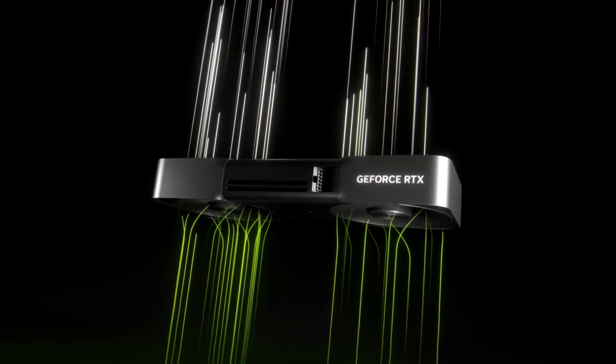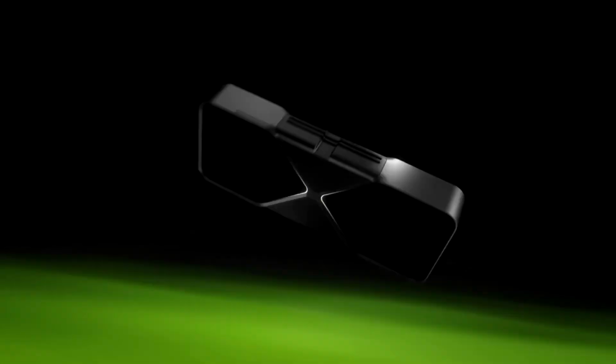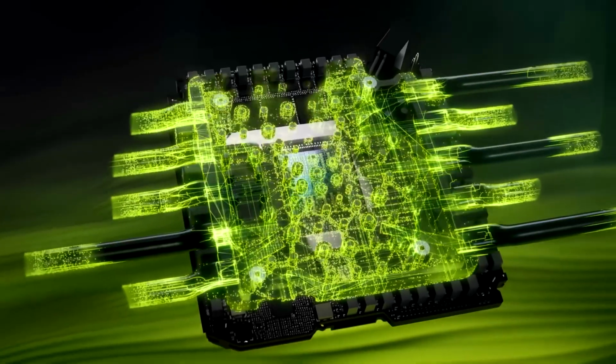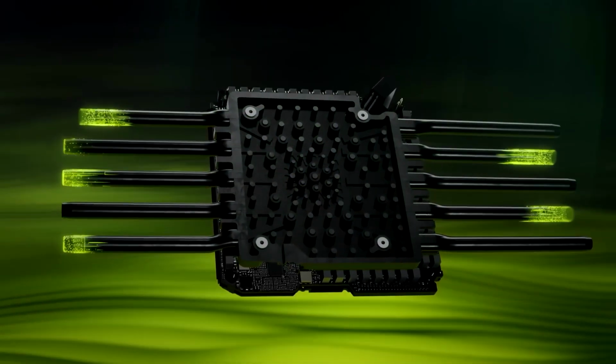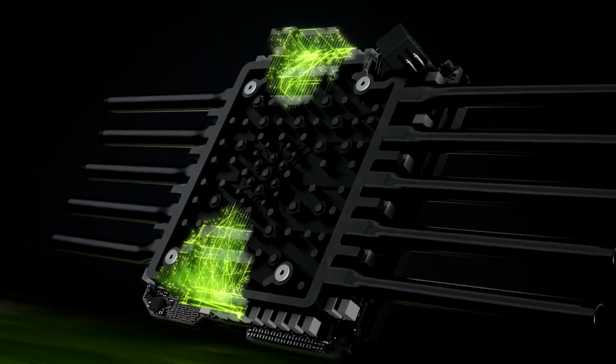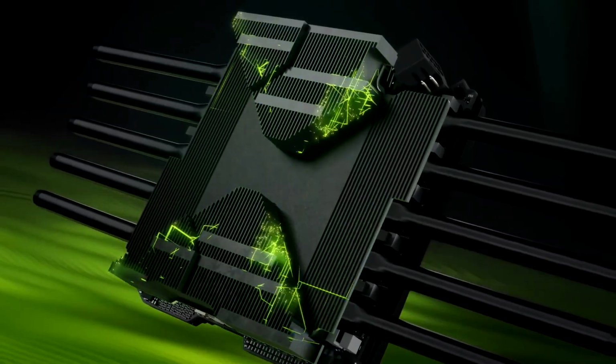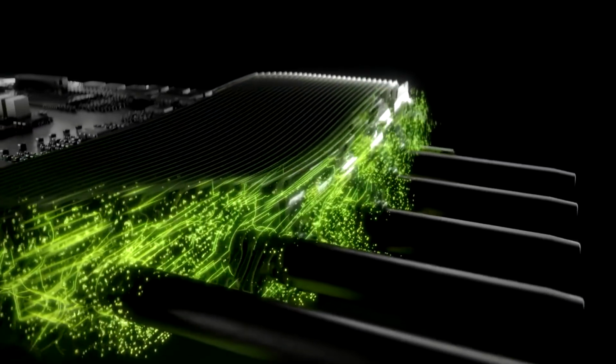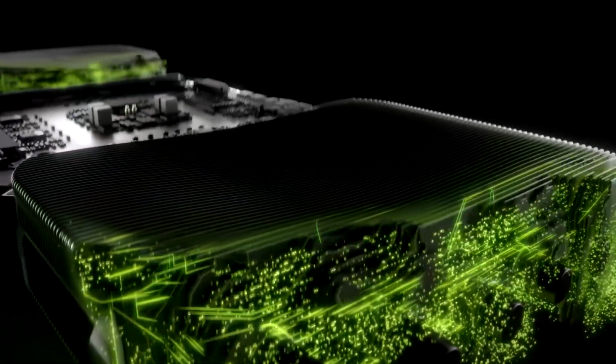extremely space efficient by reinventing the graphics card PCB layout, splitting it into 4 separate components. The Founders Edition cooler also uses a 3D vapor chamber design with integrated heat pipes as opposed to soldered heat pipes, which makes heat transfer more efficient. To further increase surface area and thermal efficiency, curved active fins are added to the top of the vapor chamber, which regulate pressure drop.